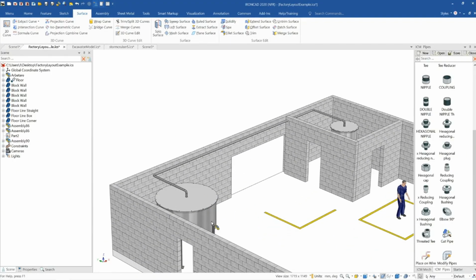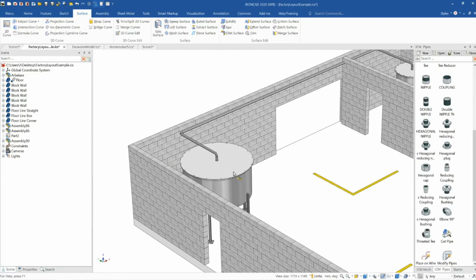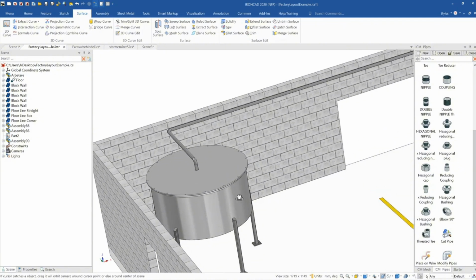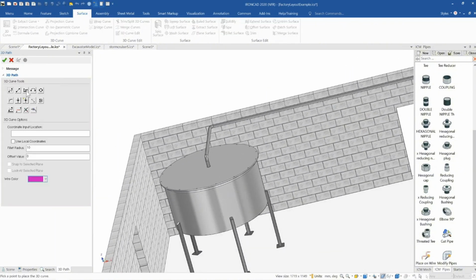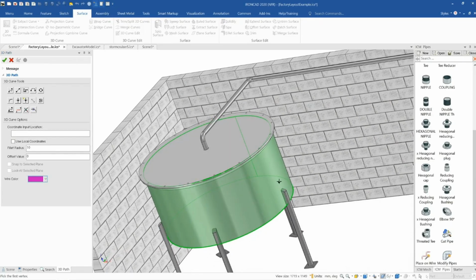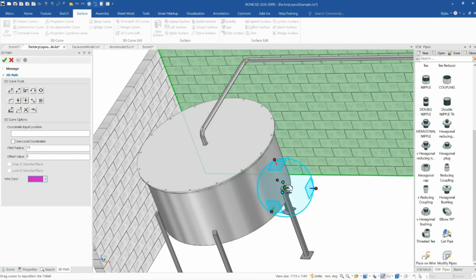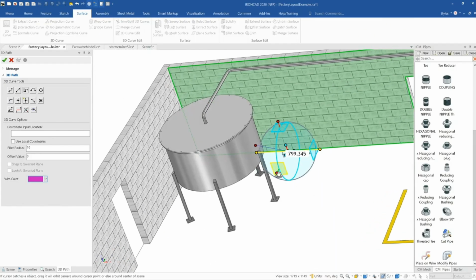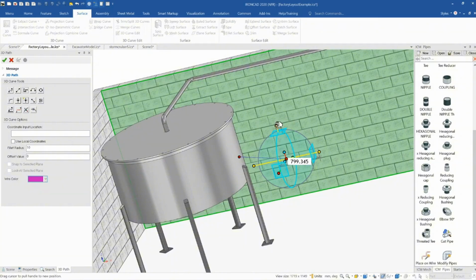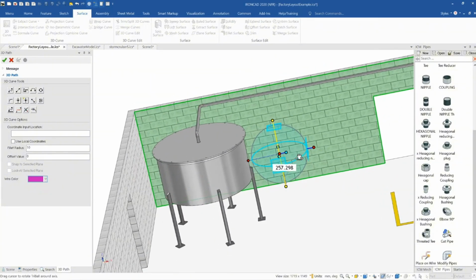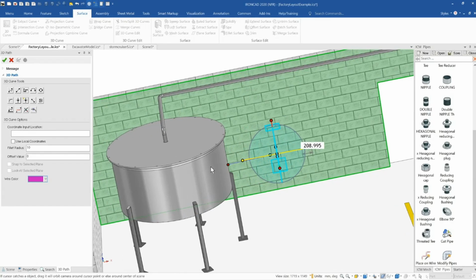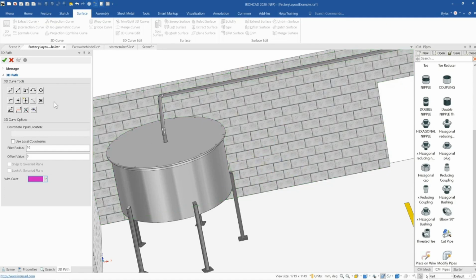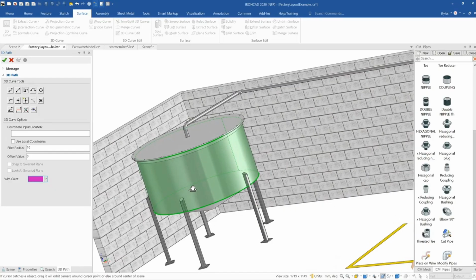Now in this case I did a pretty simple pipe that mainly went straight, but it doesn't have to be straight and only 90-degree angles. So let's create another section here quickly where we go from here. So I'm just going to start from here and activate the tri-ball now, and I'm just going to go in kind of a random direction and distance from this. Because I selected a random point, it's quite hard to snap to that. And in this case, I'm just going to pretend we're doing something kind of really strange in the direction this is going. But actually a better way to do this would probably be to place a point and then move it afterwards.